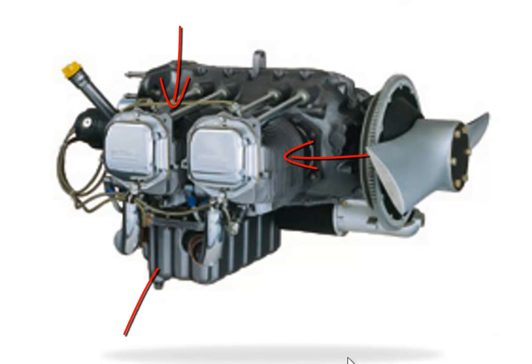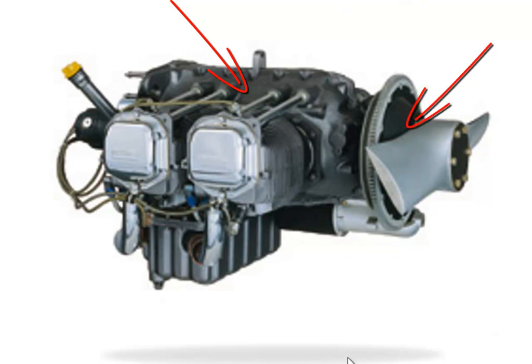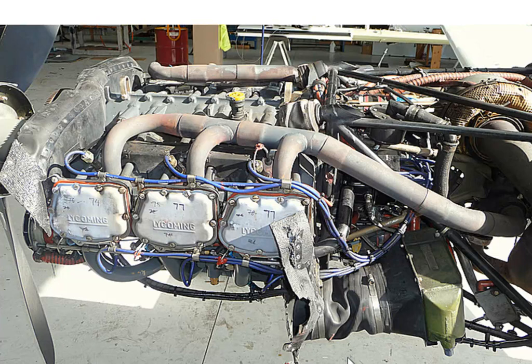This big thing hanging off the bottom is the oil pan. This oil dipstick sticks down into the pool of oil inside that oil pan. That's what you're testing when you check the oil. Everything is mounted on this case in the middle. The propeller is mounted on the crankshaft that sticks straight out the front of the engine. If this were a helicopter, the engine would be pointed in towards the transmission to convert that to lower RPM for the main rotor. Here's a six-cylinder version of pretty much the same engine.